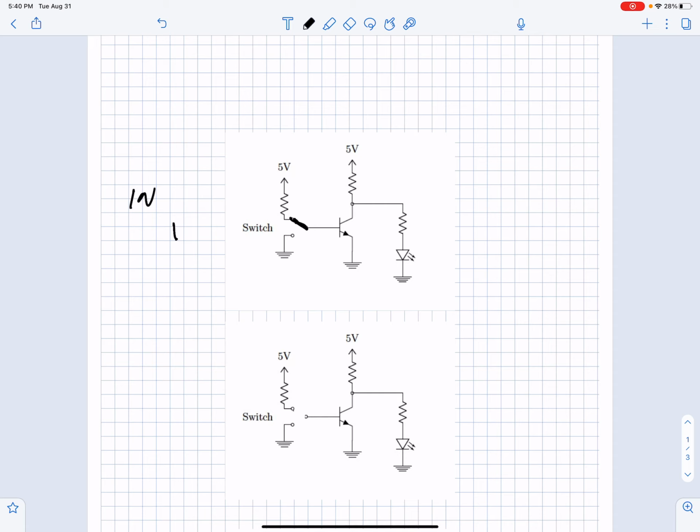In the lab, they talk about transistors acting like voltage-controlled switches. I actually think of a BJT as a current-controlled switch, but that's a small technicality because if you have 5 volts, what does that even mean, this arrow? This arrow going up means there's a 5-volt source, a battery source, or whatever you want to think of, that makes a complete circuit.